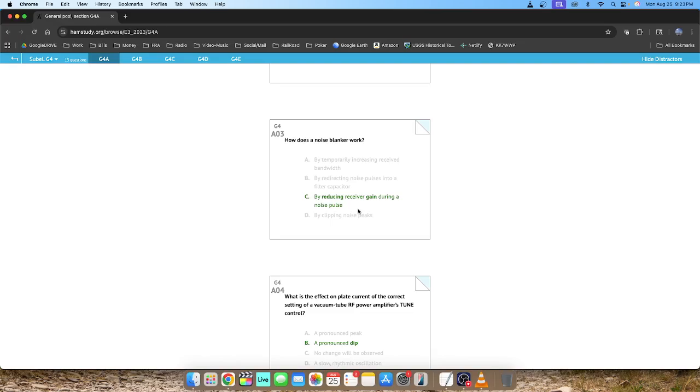Yeah, good question. So, actually, a lot of HF transceivers, even quite a few mid range ones, do come with a noise blanker feature built in. It's not usually something that's only found on the really high end radios. Even more affordable or mid tier HF radios have some kind of noise blanker because it's such a useful feature for dealing with those common types of interference. So, chances are, if you have an HF rig, there's a pretty good likelihood it has a noise blanker in there somewhere. It's definitely a common and handy tool to have.